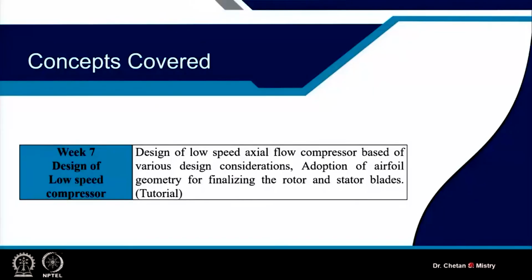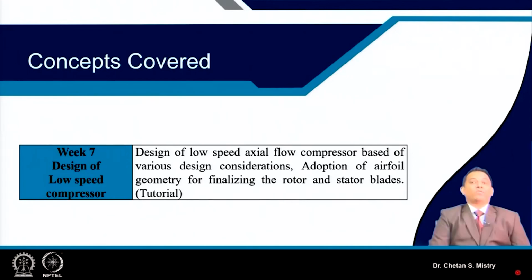In the last module we were discussing the design of low speed axial flow compressor. In that module, we discussed the need for this low speed configuration and the research that is going on in universities using low speed test rigs available with them. Then we took one numerical for design of a low speed axial flow compressor using the free vortex concept, using the fundamental approach and the forced vortex concept.